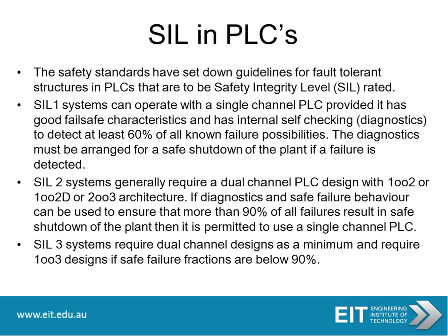Now, the safety standards have set down guidelines for fault tolerance structures in PLCs that are to be safety integrity level rated. So SIL-1 systems can operate with a single channel PLC provided it has good fail-safe characteristics and has got an internal self-checking diagnostics to detect at least 60% of all known failure possible. And the diagnostics must be arranged for a safe shutdown of the plant if failure is detected.